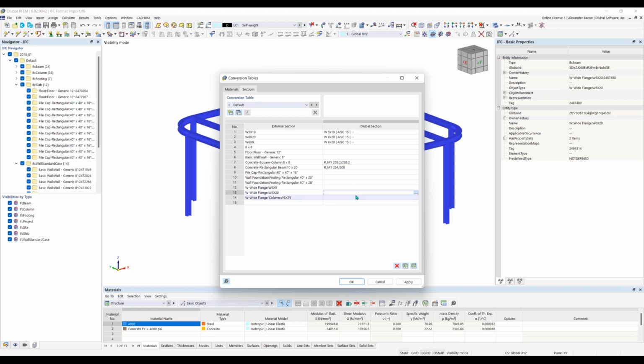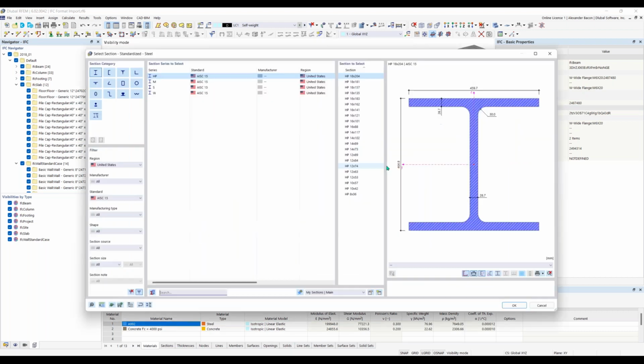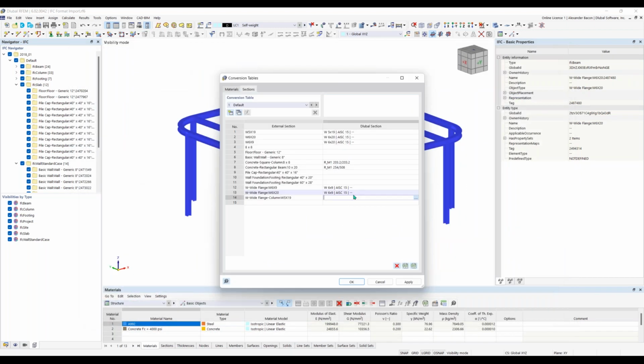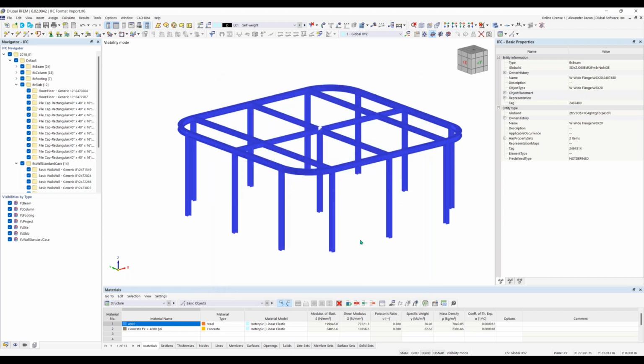And then what I can do is simply hit F8 for the cell below there. So we can hit the next cell, then hit F8, and then hit F8 again, and fill out these rows here. And then for these, instead of having to go through the material library, we can simply edit them. So I can change this to 5x19, like that. So now we have our cross sections entered for the steel structure behind this window. I can click OK.